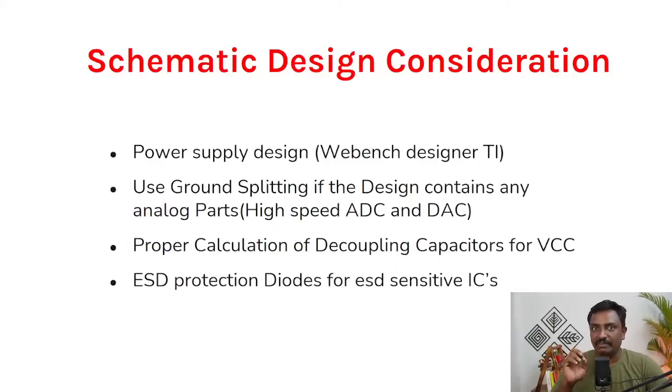There is software available. One problem with the WEBENCH Designer from Texas Instruments is that it only recommends Texas Instruments parts. Sometimes the cost would be quite a bit higher than other parts available in the market. But it will give you the entire schematic when you design a power supply using WEBENCH Designer. The next thing is you have to do proper ground splitting, otherwise your board will not be reliable.